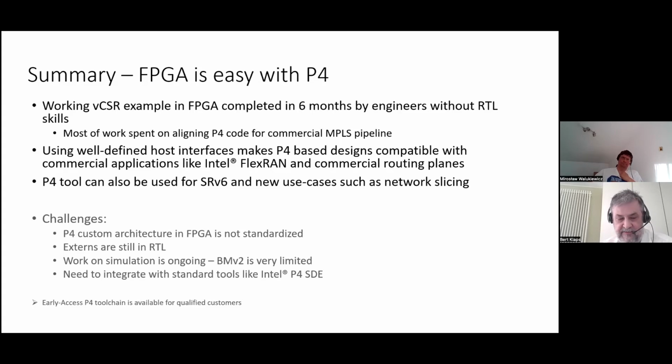The challenges we encountered during this development: the first one is on the architecture. This might be a bit surprising, and it's a consequence of the flexibility of the FPGA. Normally an ASIC or an ASSP, like a programmable switch, has a P4 architecture which is fixed. It doesn't change, and you just fill in the P4 pipeline with your P4 program.